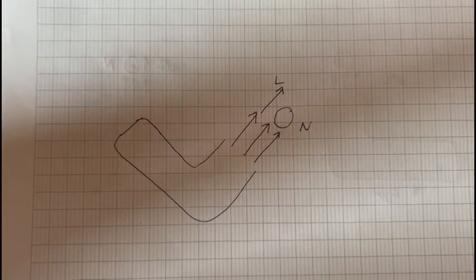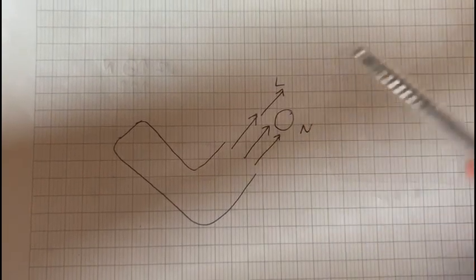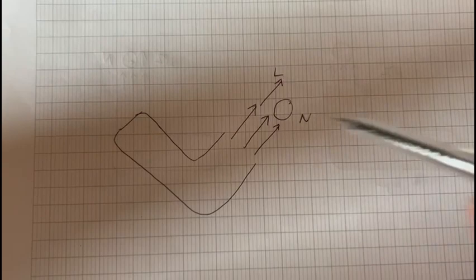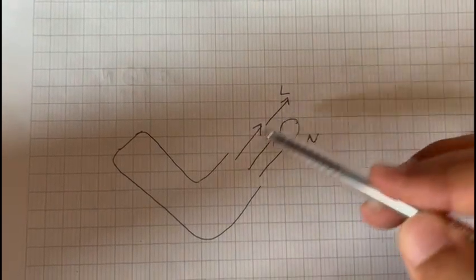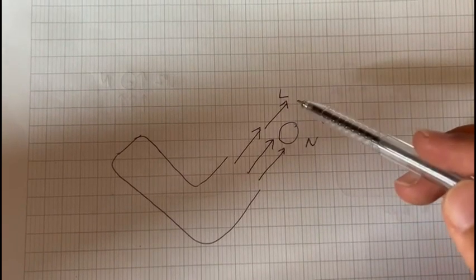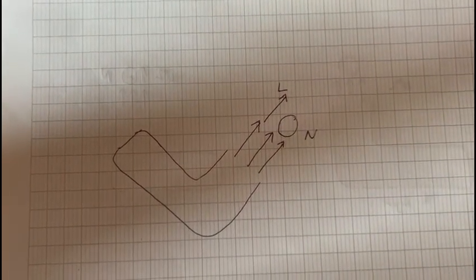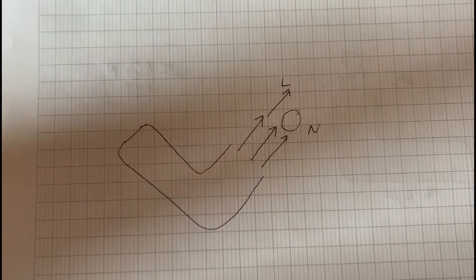And when we tilt the hairdryer, this is what we would notice. The hairdryer is tilted and the air goes at the angle that it's being tilted, and the ball consistently stays on one side. The air passing from the other side creates the low pressure zone again, and on the free side there is normal pressure. So again, this pressure difference is what keeps the ball in the stream of air.